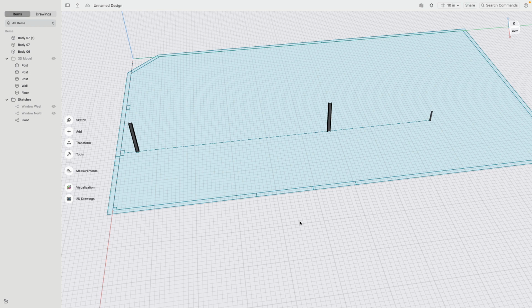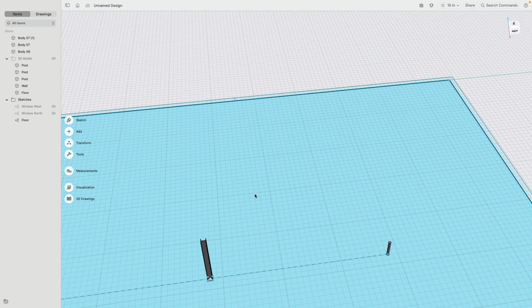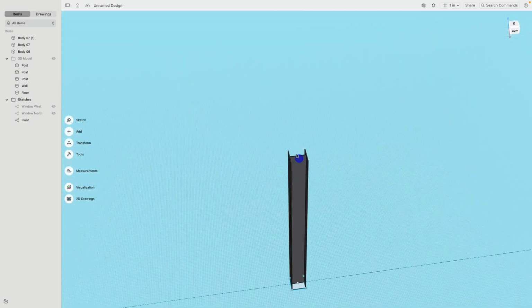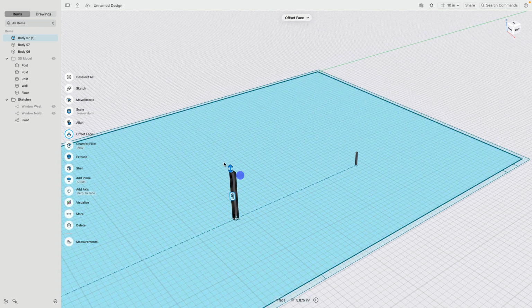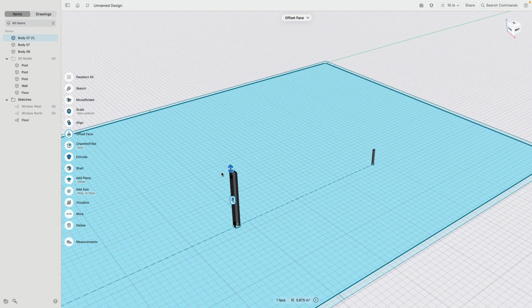Since we have the position of the vertical elements, it's now a good time to work on the horizontal elements. So let's go to this I-beam there, and I click on the top surface. Now this is 95 inches, and this part should be 136.25 of an inch.